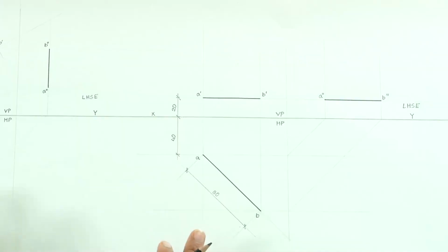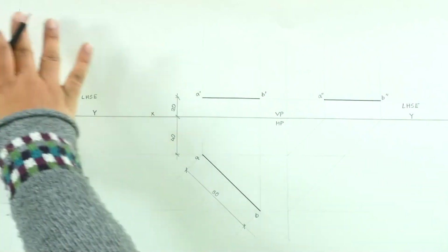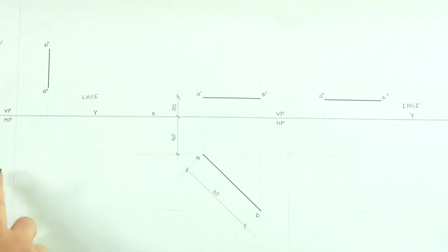So, the point is not just about the technical correctness, but it is also about how you make your sheets look better. Another word of caution: I am familiar with how to draw, so I can directly darken the lines here. Do not copy me here. You should always make the entire drawing very light, almost as dark as the projection lines, and then gradually start darkening it from light to dark. The darkest lines should be drawn last, so that they do not smudge.